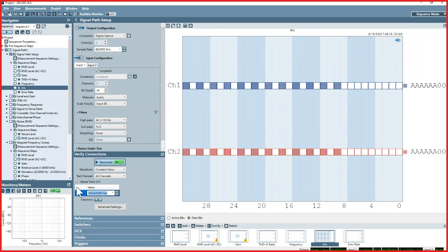So this is just a very simple data pattern. If I was looking at this on an oscilloscope, I'd directly see the high and low bits of the actual data word on the oscilloscope. And if data was getting mangled, I'd see that right away. So this just generates a constant pattern for the digital word. It's really not audio data at all.